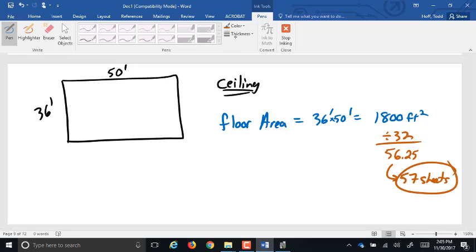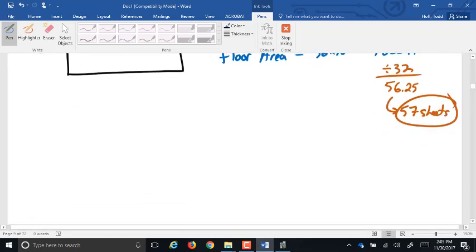If you ever get into some of the larger builds, they actually put up the exterior walls and then sheet the whole ceiling, and then go back and build the interior walls. Partly because then you get less cracking on the sheetrock where it meets the sidewalls. Another reason is just plain faster. You don't have to cut around the interior walls as you're sheetrocking the ceiling. But it is pretty common now.